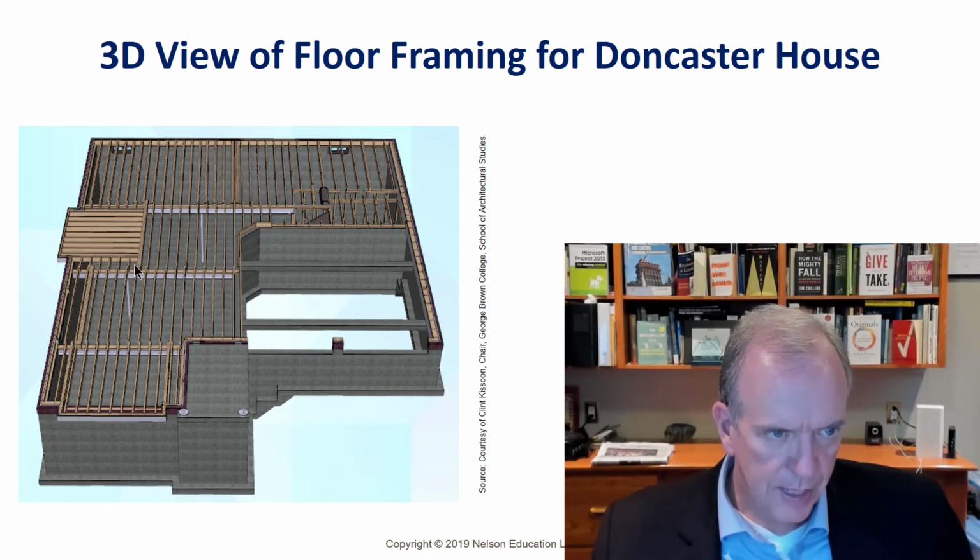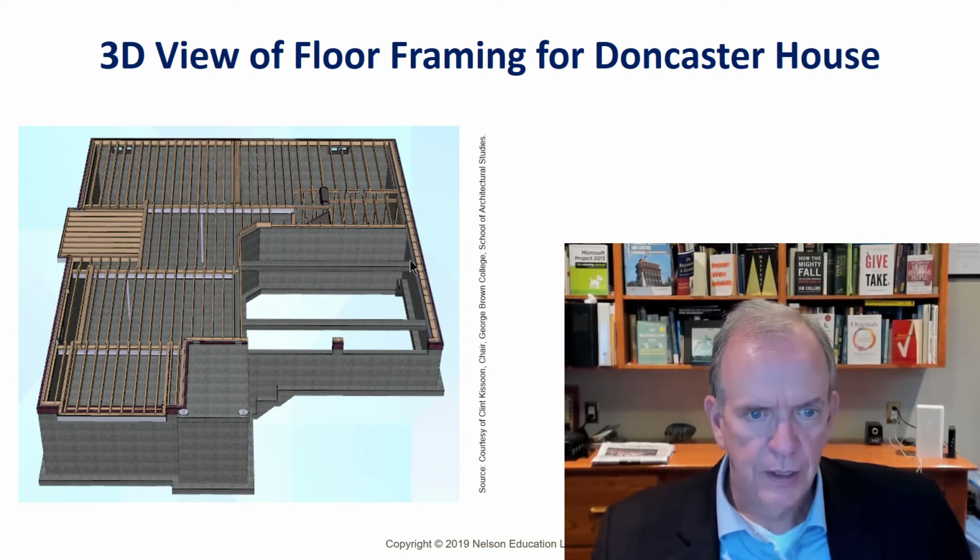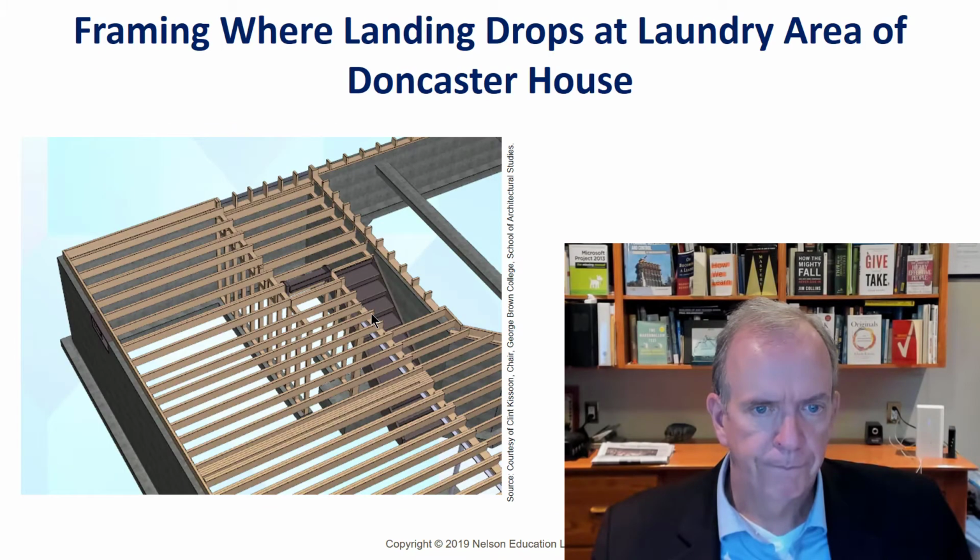And this here is that cantilevered box window that we looked at in 3A and 3B. These are grade beams that are put in place, and that's to help stop the sagging of the concrete pad, because this is put in on fill, and the slab for the garage slab is put over that. So this is all going to be filled in with earth and compacted before this is poured, and then this gets poured with the garage floor later on.